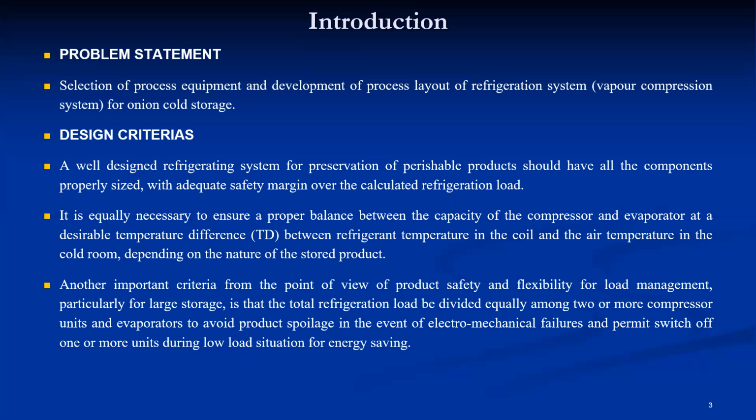Especially for large installations, standby units are a must. If you choose only one unit for a particular capacity, then in case of any failure the entire plant will be shut off. So a standby unit is essential.